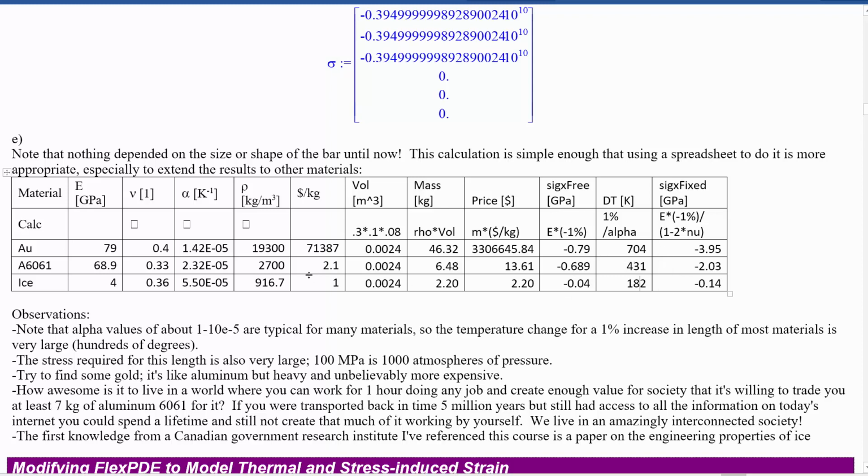That said, some materials do have different thermal expansion coefficients than this and move a bit more, so that can be more dynamic. But if you wanted to make a really good sensor for temperature, then you can instead exploit curvature. Get two objects that have a different thermal expansion coefficient, hammer them together into a thin strip, so that then when one of them tries to expand more than the other one does for a temperature change, it's going to lead to a curvature.